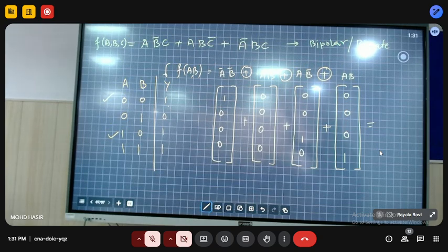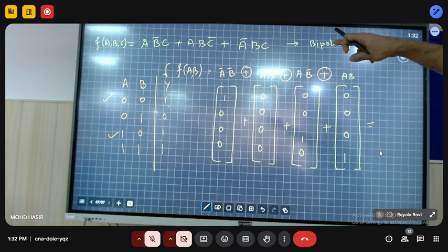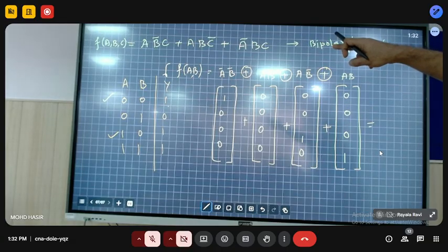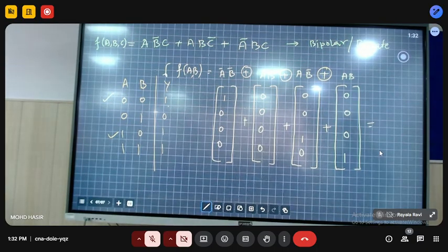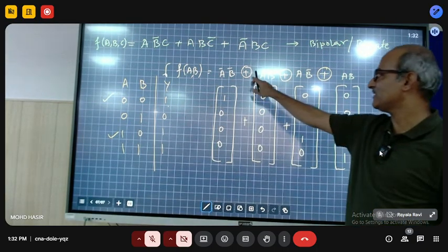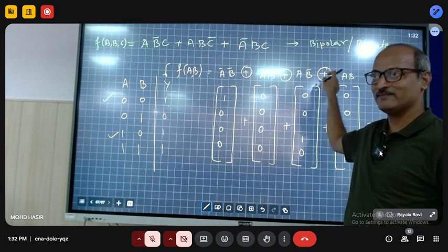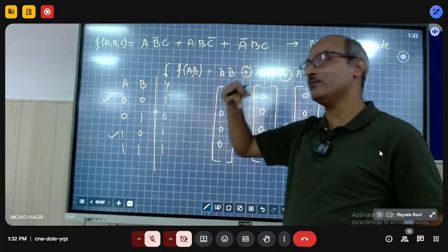Now you go back to your PLA, PLD, and you will find that there is a XOR sometimes. Why? Because it permits output, and SOPs, and OR implementation. That OR gate can be replaced with XOR gate. Under this consideration, if I use this as a programmable inverter, SOP can be turned into POS.